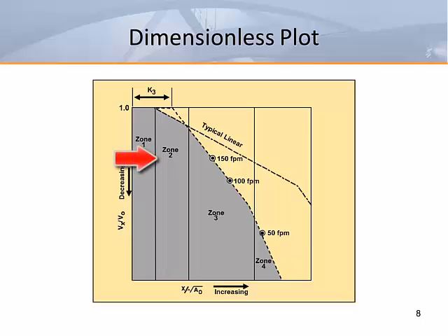In the second zone, the jet begins to mix with room air, causing the jet to expand. Linear outlets typically have an extended second zone. The third zone is where most of the induction occurs. This zone has the most effect on room air velocities and room air induction.